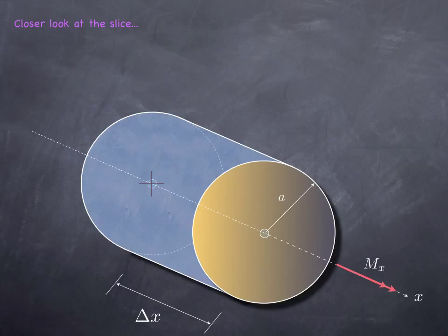I'm going to isolate a little plane section in this little segment of the circular shaft and observe its deformations due to the applied torque. So I'm going to highlight a little plane delineated by these three yellow lines, as well as the dashed line that is running across the center of the circular shaft. I'm also going to put a plus mark on the back side of this little patch, demarked by these yellow lines. This plus mark will be made onto the side of the circular shaft, and it is going to have a 90-degree angle between its two legs before the torque is applied.